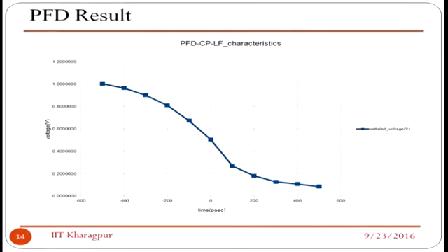when there is a phase difference here 0, and then if I shift my VCO divided by n frequency left or right, I will see that the charge pump and loop filter will generate the voltage in this manner. Of course, this is not very linear, but around the locking time it is almost linear. So the slope of the curve actually is the PFD, charge pump and loop filter gain. So you have to calculate, but finally you can also get the PFD CP characteristics this way.